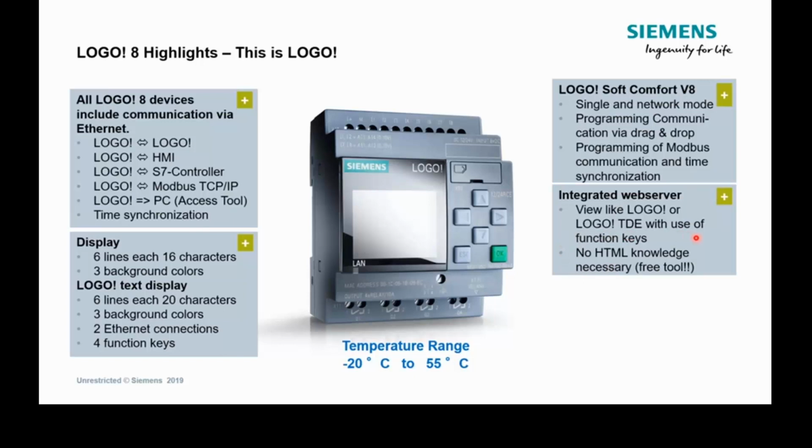So we issue a free tool, the LOGO! Web Editor. We'll have a look at that as well later on. That uses a what-you-see-is-what-you-get format, so you drag and drop objects into an editor field and then you tag the addresses up via drop down menus. So it's very easy to generate these web pages without any special programming knowledge.